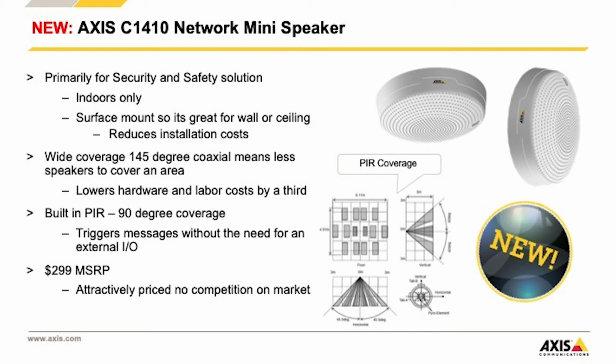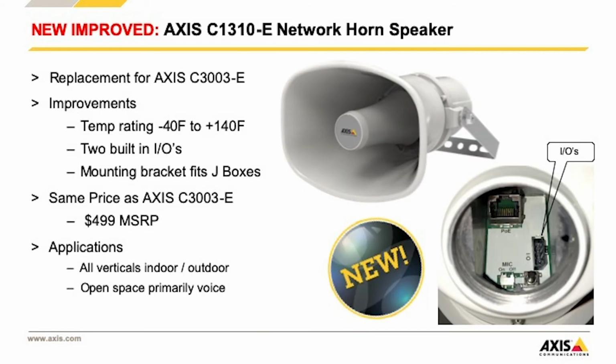So what's an application for that? Let's say you have a facility and people are constantly using an emergency exit to go in and out of the building. And you want to stop that because obviously security might get a message each time the door is activated. So you put the speaker in that area with a PIR pointed towards the door, obviously. And if somebody goes near that door, it'll play a message saying this is an emergency exit, please do not use.